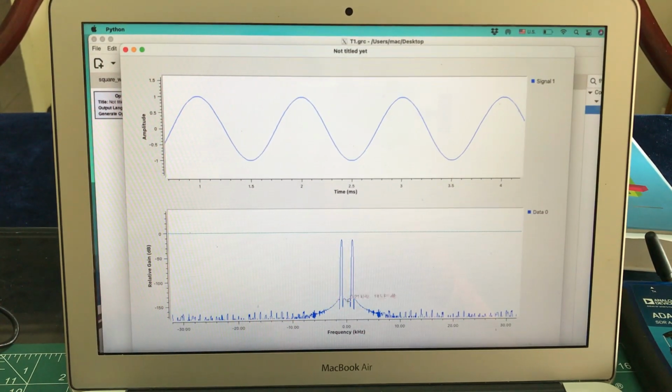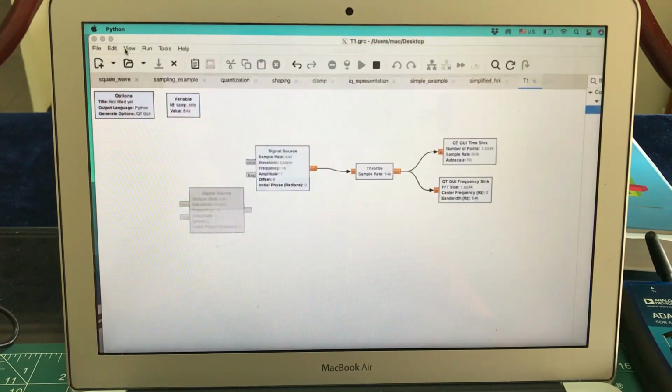By zooming out, as you can see, this is the actual signal that I'm interested in, because this is on the positive side of the spectrum. There is no such thing as a negative frequency. But if you have seen my tutorial on Fourier transform, this comes from Euler's identity. In a physical device, you won't see the negative part, but in simulation you can see that indeed you get F minus FC, F plus FC. This is how you actually visualize this.